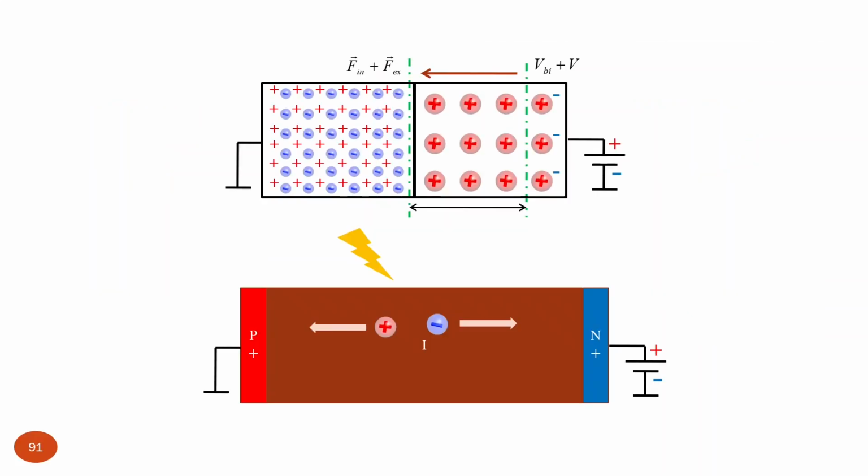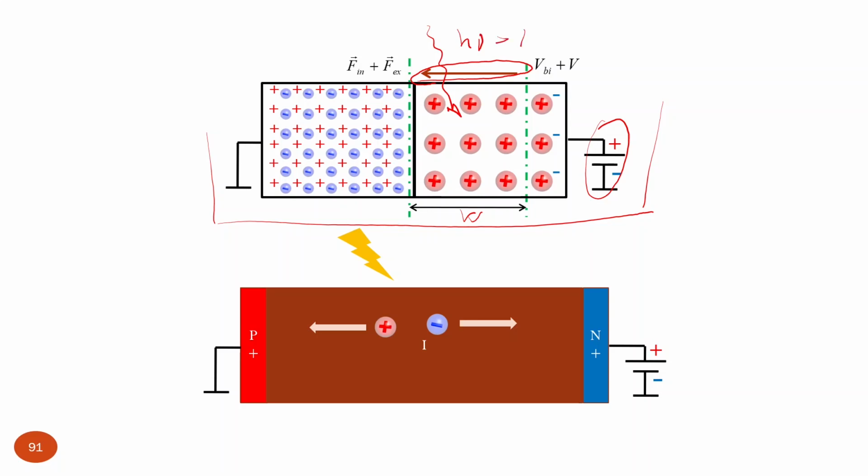So there could be two types of photodiodes. First, it can be based on the traditional, for us already, PN junction configuration. That's this first figure. Then we apply some reverse bias. We make the width of the depletion layer as wide as possible. We know that there we will have a large internal electric field, and any charge carriers generated here with photon energy larger than the band gap of the semiconductor material, these photo-generated electron-hole pairs, will be efficiently separated by this strong electric field and contribute to photocurrent.